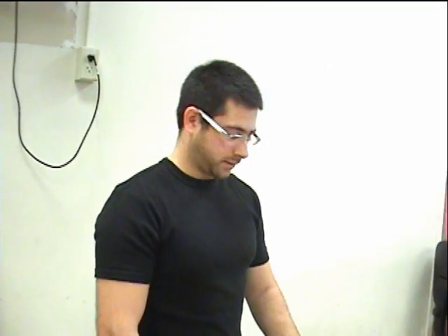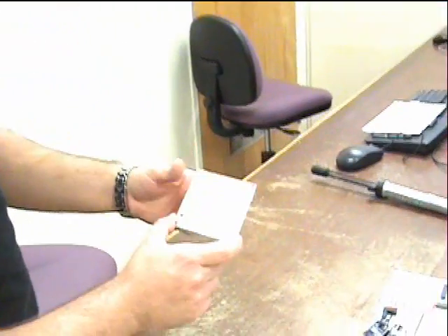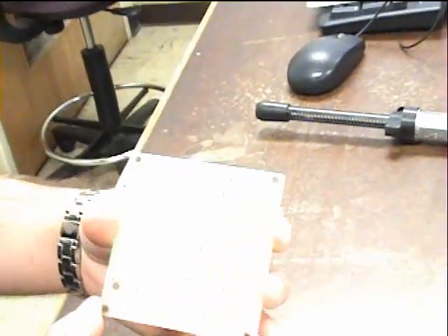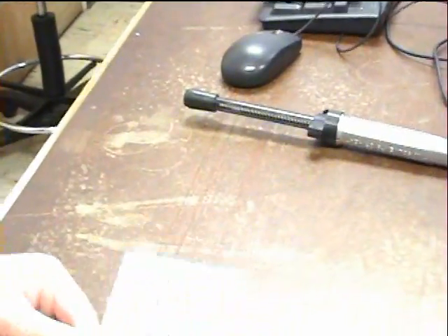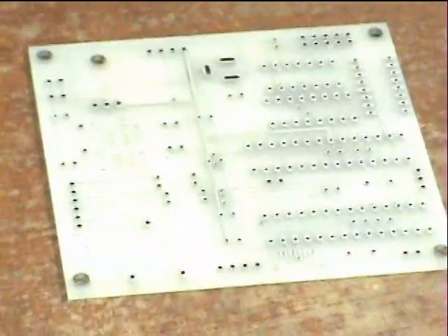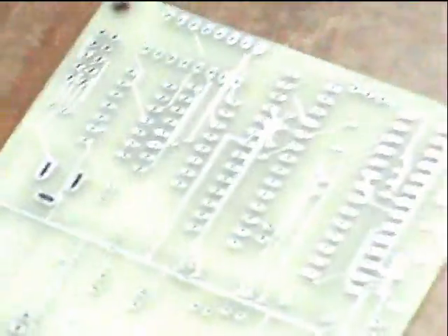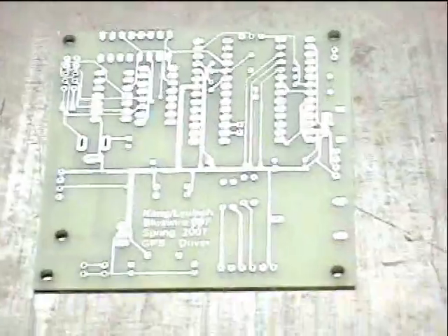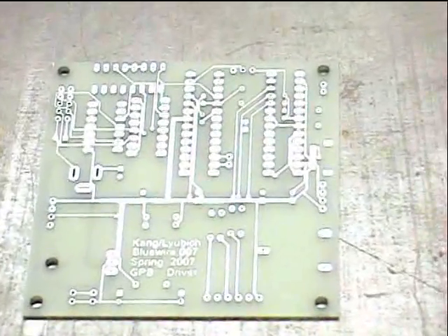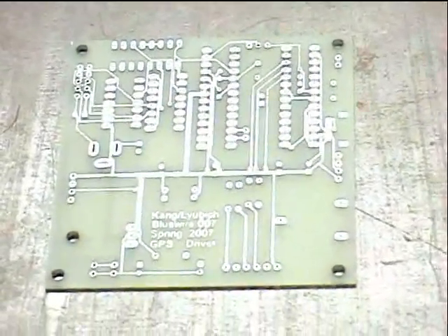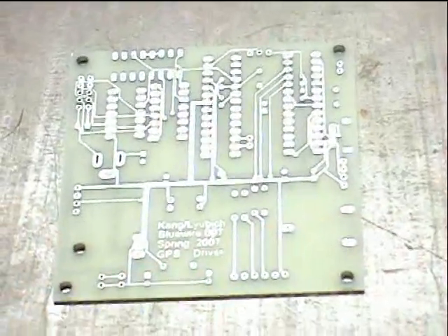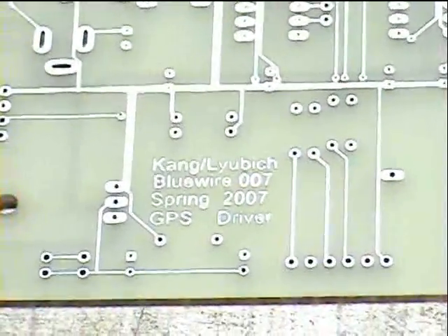So now we're going to introduce how we ended up with the final PCB. So the first thing that we did was we ordered our first prototyping board, which is a little bit bigger than the actual final prototype. It doesn't have any silk screening or solder mask for testing purposes. It does include 2 microcontrollers and all the ports for the sensors and the lights and the motor controls. And it's a little big, but this was the first prototype.